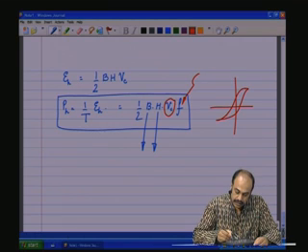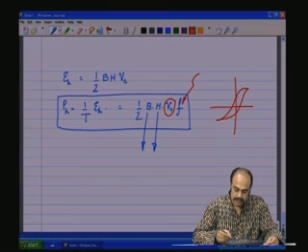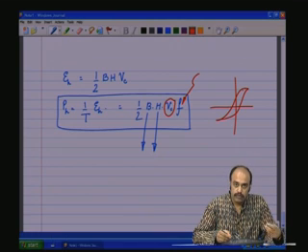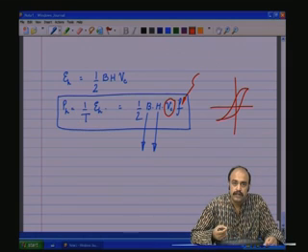One traversal of this hysteresis loop means this area is covered, and that amount goes into what is called the hysteresis loss, which is unrecoverable. If this is traversed more times in a second, you are going to have more loss, which is the frequency issue coming up here. Higher the frequency, more number of times this hysteresis loop is traversed in a second, therefore, higher is the loss. Therefore, hysteresis loss is also proportional to the frequency of operation.